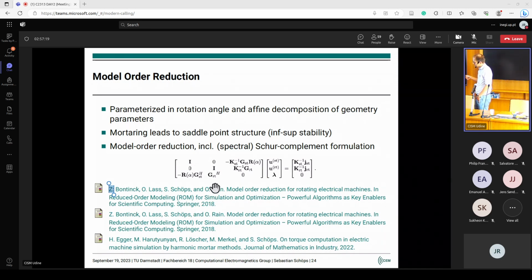So either we used model order reduction for this, which is in the nonlinear case almost necessary. But if the problem has no additional nonlinearity in terms of material properties, what works quite well is to formally invert that matrix. So you don't really include an inverse, but what you do, okay, let's start here. This is the Lagrange multiplier, and these are the unknowns. So these are finite element many. So in 3D, these are 3D degrees of freedom. And then this would be an interface, so 2D many. In 2D, those are 2D many, right, in the plane, and the Lagrange multiplier is only on the interface.